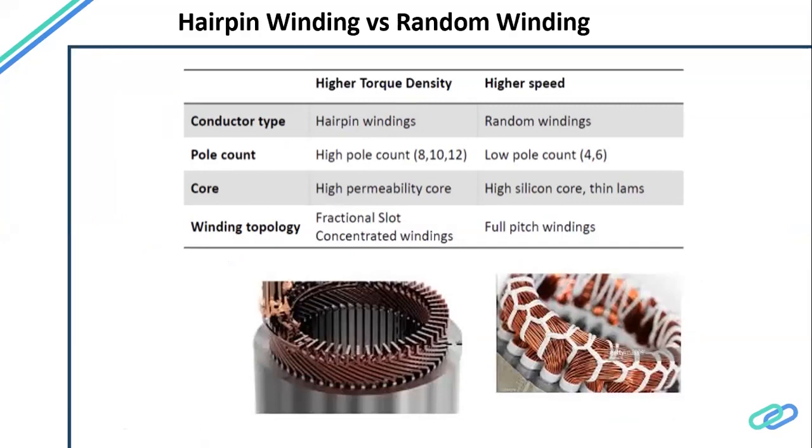As we will see, for some of these, if you have very small volume or want to start something, we can definitely switch from this winding to this winding, or back and forth. We have to redesign those, but definitely thermally, it is better to manage this kind of winding than the random windings. We will also take up this as a topic for further detailed discussion.